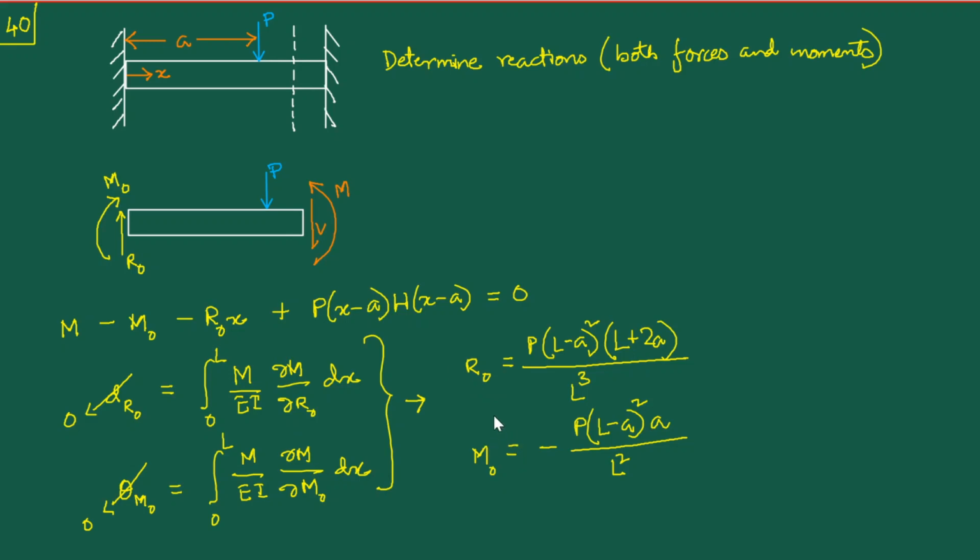But you note that if for a simple cantilever problem you obtain these answers, then definitely these are going to be wrong, because if you just apply statics, as you have all learned in our first year mechanics, the reaction force at this end is simply P, and the magnitude of the moment is simply P times A. So these answers are definitely wrong for a simple cantilever problem.